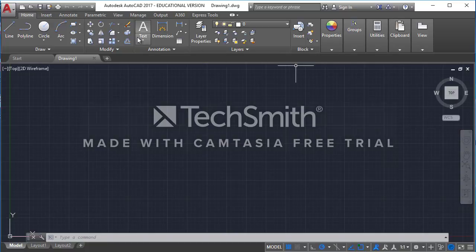Moving on from Annotation, you're going to notice another area called Layers. Just like InDesign, Illustrator and Photoshop, AutoCAD also works in layers. You use layers to organize all of the different line work that you have. You're going to have a layer for your exterior walls, for your interior walls, for your doors, your windows. You'll have a layer for everything so that you can easily turn things on and off as you need to.